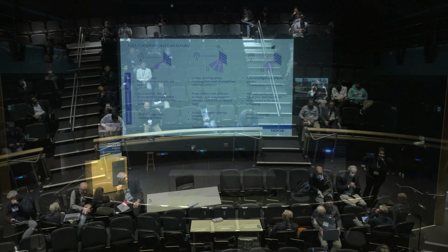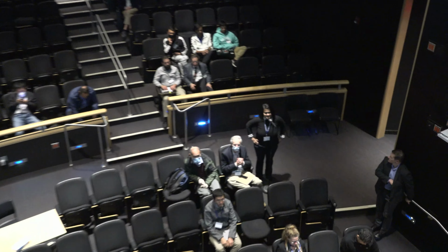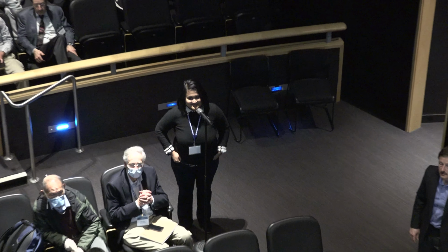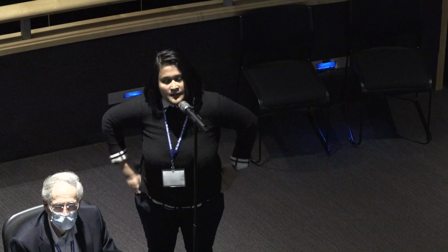Hi, very nice talk. I really like the fact that you took a skeptic's point of view. You looked at what can or cannot be done and hashed out these three possibilities of using them in fully, partially, etc. reconfigurable mode. My question is, you mentioned that signal processing can play a big role in this fully reconfigurable setting. In conventional phased array antenna arrays, a big advantage is that I can do digital beamforming. Suppose I want to do adaptive beamforming or minimum variance distortionless beamforming. It's a very popular technique in radar to maximize your signal to interference plus noise ratio.